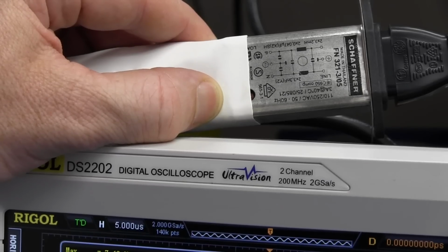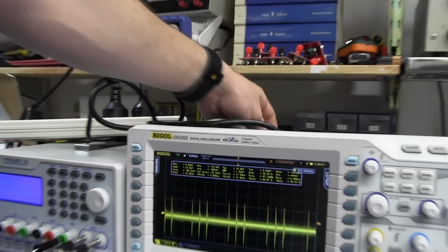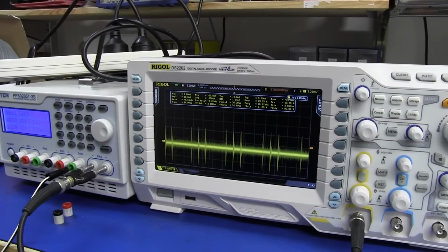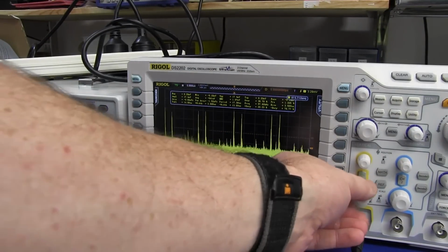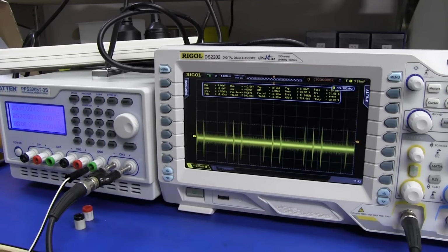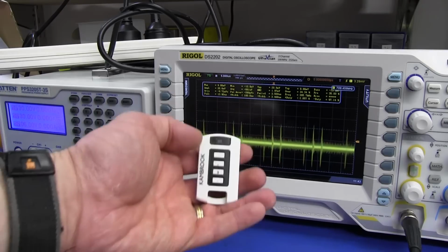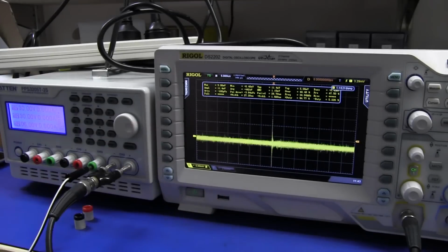Now, even if I power both the scope and the power supply through a mains input filter board, so I've got both bits of gear, that's the only thing off that filter, we're still picking up this pain in the ass common mode noise here. Look at that. So what's that coming from? Well, we go full circle back to something that we tested before. Our lights. Let's turn it off. Look at that, folks. Bingo.